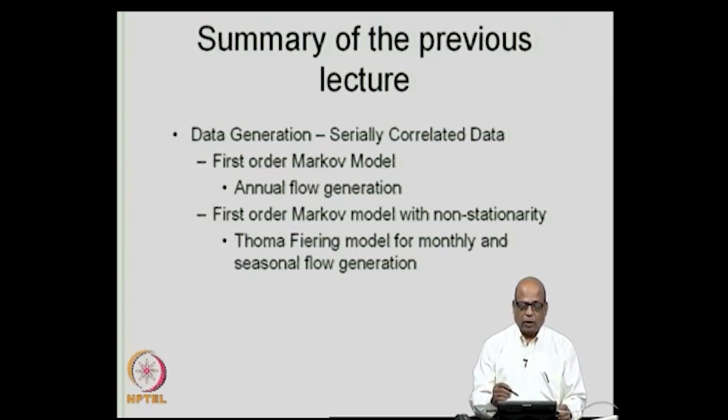We incorporated that into the Markov model. This in the hydrologic literature is famously known as the Thomas Fiering model, and typically it is used for flow generation for monthly and seasonal time periods, and in some cases it has also been used for smaller time intervals like 10-day and fortnightly time intervals, etc.